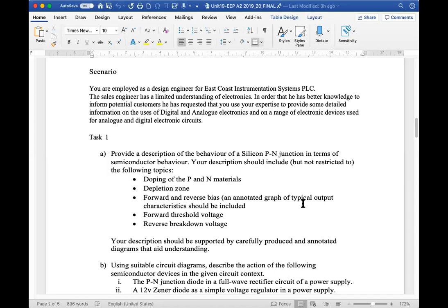Part D is pass. You're given the application of a strain gauge that provides an output in the range 0 to 200 millivolts across its sensing range. In order for it to be interfaced with an instrument to display an output, this signal needs to be amplified to have a range between 0 and 5 volts. Going to incorporate an operational amplifier like that in figure 1.